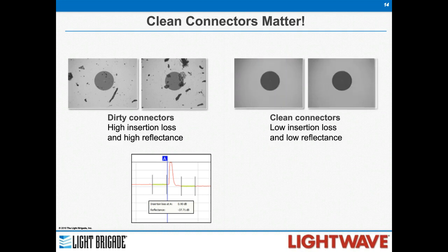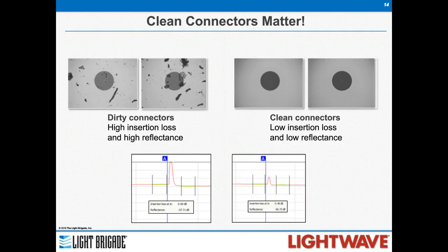We took a fiber optic cleaner. In this case, we used one of the one-click cleaners. You can use one of the real cassettes. You can use a wipe or a stick, whatever you like to use, but we used a fiber optic cleaning product. We cleaned the endface. We remeasured the same connection, and now we had 0.48 dB and a minus 56.7 return loss.